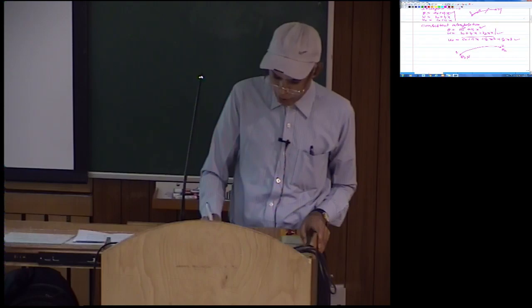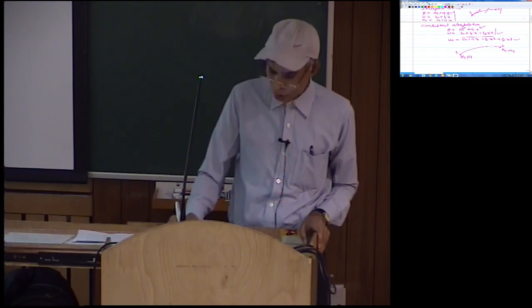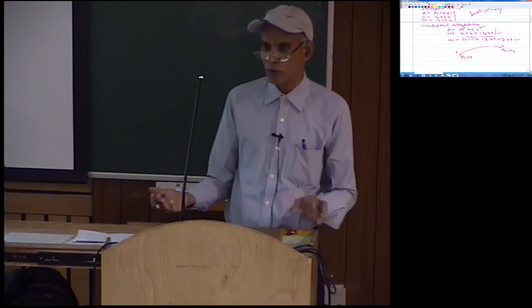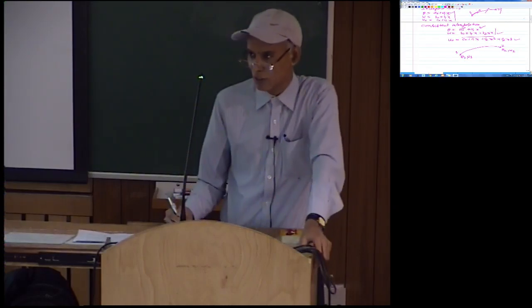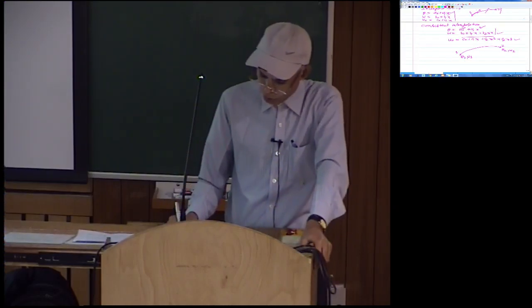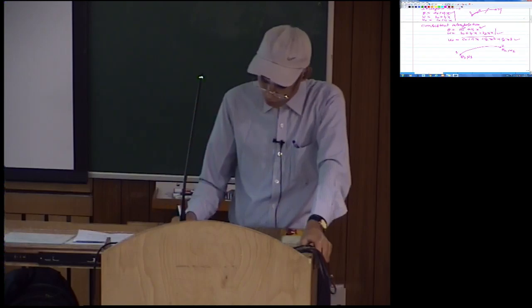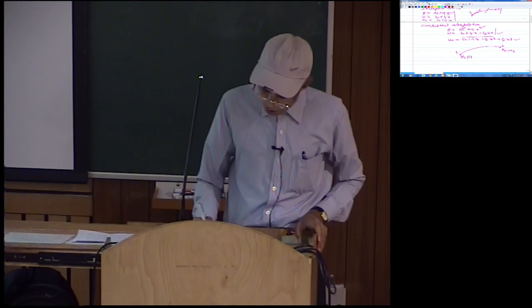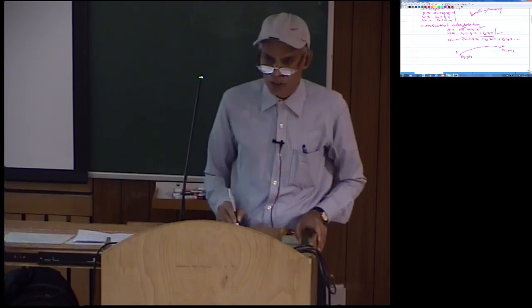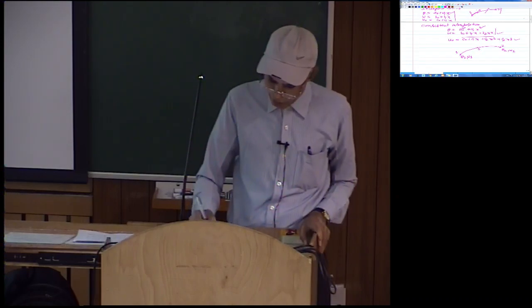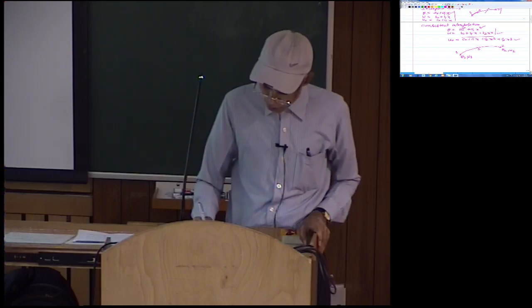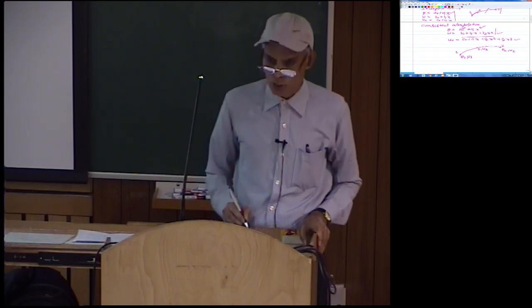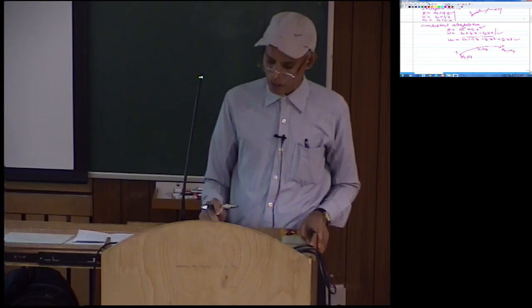So one we can have here w1, here we can have w2, so that we ensure the continuity of w across the elements by taking the same values of theta and w at the common node between two elements. Then we need a third node, so we can have an intermediate node here. Let us say that's the third node, and here we will have the degree of freedom, let us say, w3, but no theta degree of freedom at the third node.